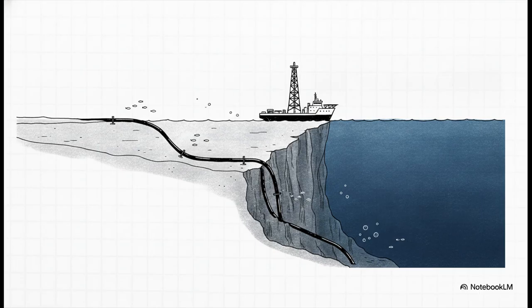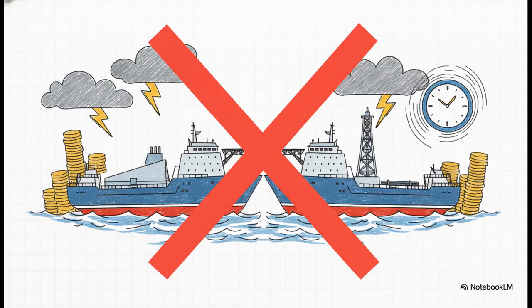You might think you'd swap vessels, but the answer is almost always a single J-lay capable vessel for the entire route, even in the 200-foot shallow sections. While J-lay is absolutely an ultra-deep water specialist, it can still technically operate in shallower waters. It just does it at a much lower production rate than a dedicated S-lay would. And the reason for this boils down to cold, hard economics. Remobilizing a second vessel mid-route to switch lay methods is astronomically expensive. Bringing in two massive, specialized offshore vessels introduces tremendous schedule risks, weather delays, and mobilization costs that will utterly destroy a budget. You have to cater to the most extreme depth requirement of your route.